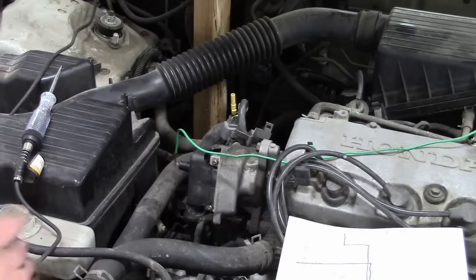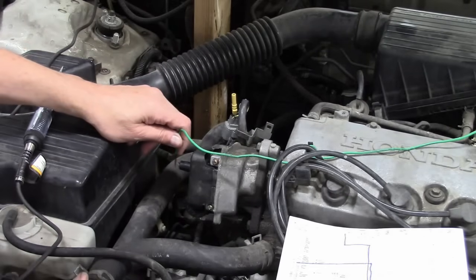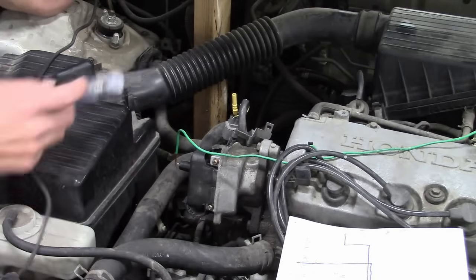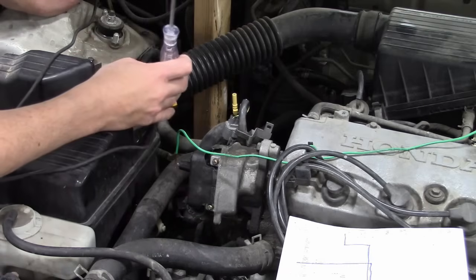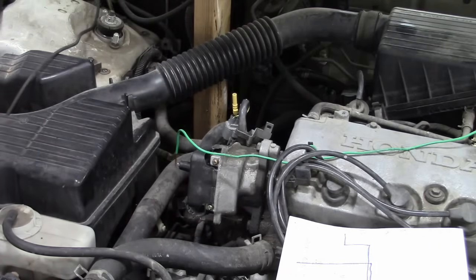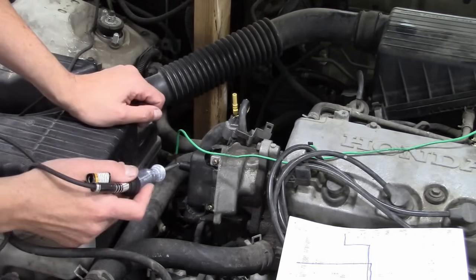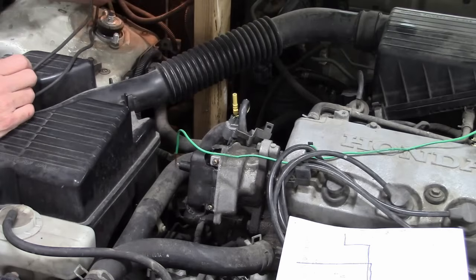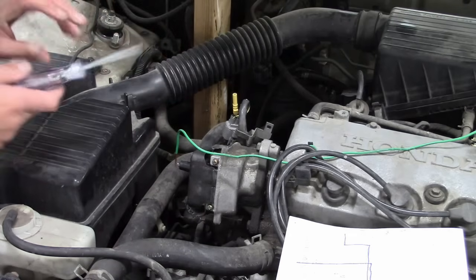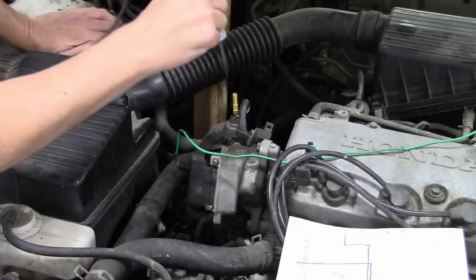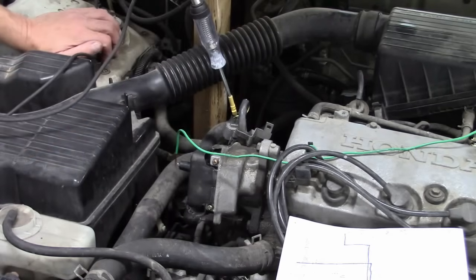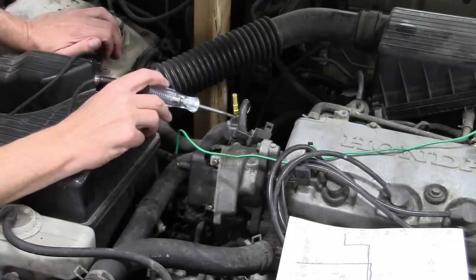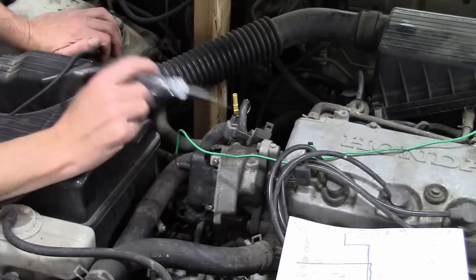So let's try that. I'm going to keep my little sparky guy there so that if I do produce spark, since I'm working around this area, it's less likely to jump to me. We've still got our test light on the battery negative, so let's touch it to the battery here and make sure. And yeah, you can see just on the corner of the screen, the light lights up. What I'm not going to be able to do is put that test light in there and expect it to light as I crank the engine.